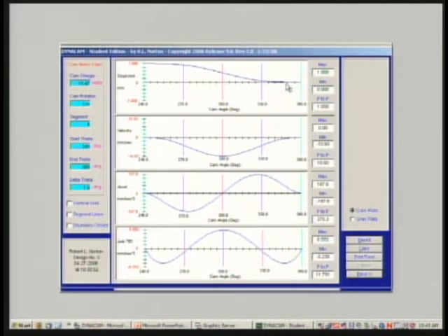Virtually nothing is happening over the first 10% of the time here, which means I could actually have increased my time, that is, increased my beta, which would reduce all of the peak values here, and still had the smoothness of the continuous jerk function, but perhaps, not perhaps, I would have some reduced values of acceleration at the peak.